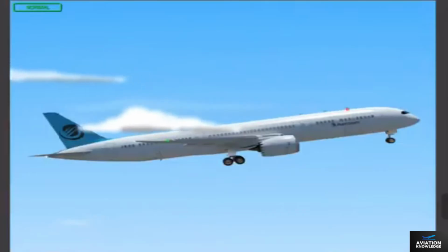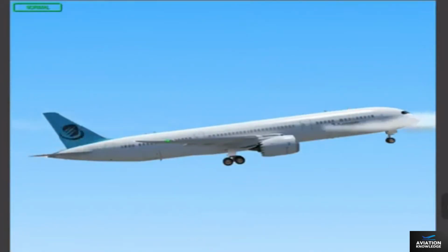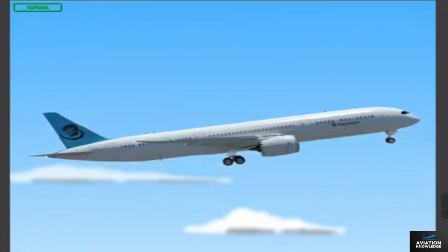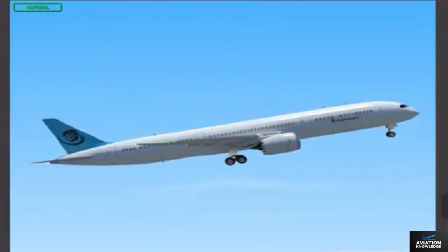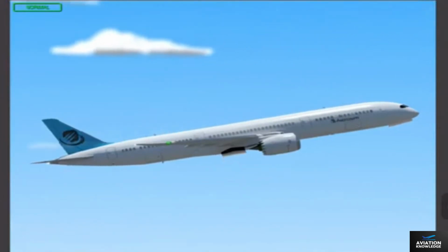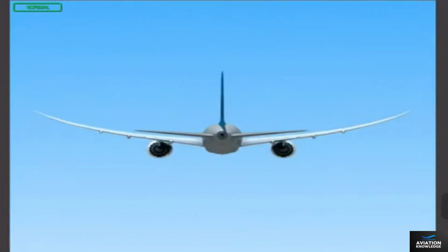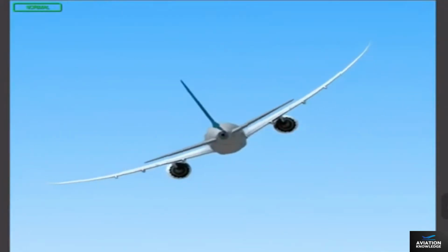The PFCs provide pitch compensation by utilizing control surface commands to minimize airplane pitch responses to thrust changes, configuration changes, turbulence, and turns up to 30 degrees of bank. The PFCs automatically control pitch to maintain a relatively constant flight path. This eliminates the need for the pilot to make control column inputs to compensate for these factors.